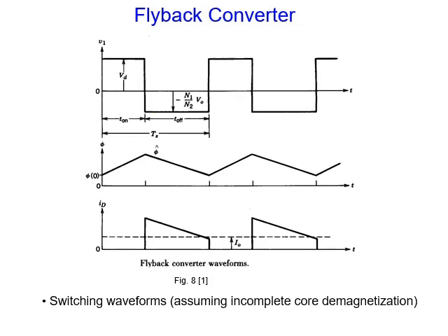So if I come to V1, V1 is the voltage across the primary. It is the input voltage when the switch is on, and when the switch is off, it's not connected anymore to the input, so it's connected to the output. So if I transfer the output to the input, I need to multiply by the turns ratio.